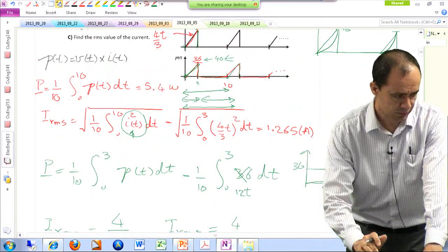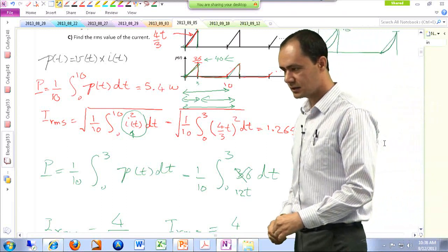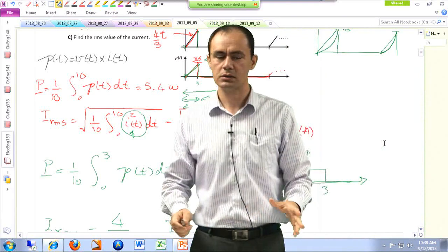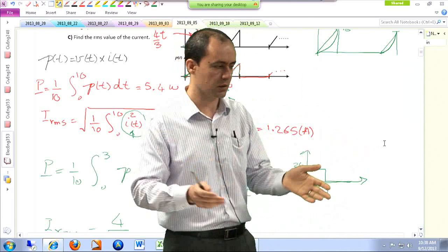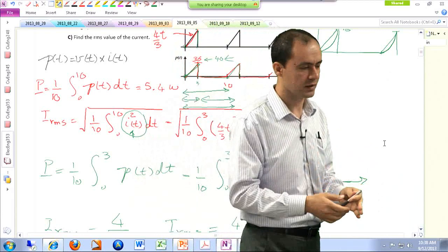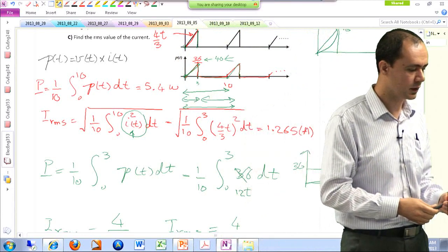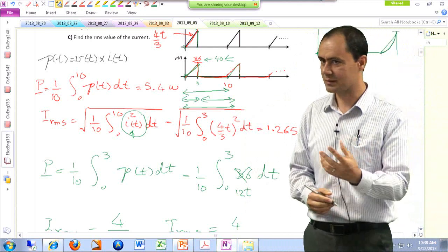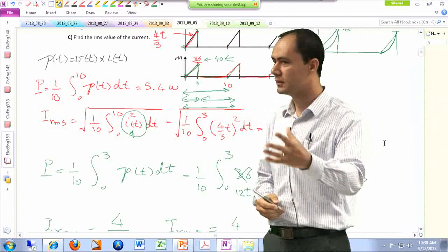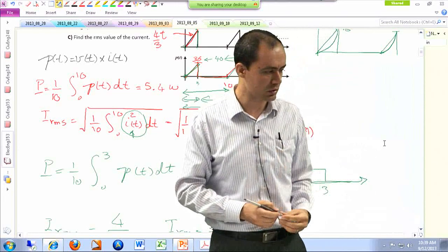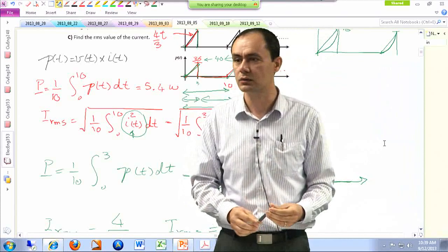So please remember, when you're trying to find the RMS value of the signal, the short answer is not whatever the peak is divided by square root of 2 or 3 or whatever form factor you can find. You really have to look at the signal, examine the signal. Always go with the fundamentals. Go with the very original definition for the RMS value of a signal.